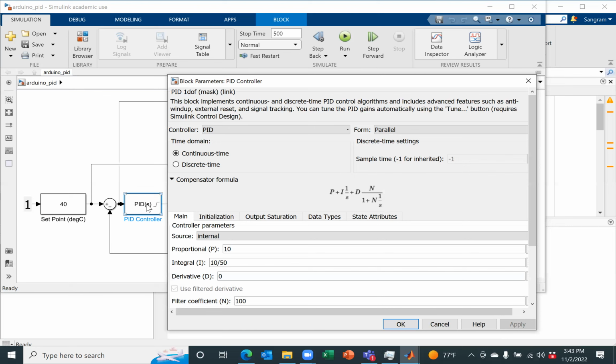So once the system is built, you run some experiments, get data, construct the model based on that data, and then use that model to find out the PID gains, and then use those PID gains for controlling the system. At the end, you will notice the model is the first order model, so simple proportional and integral control works.